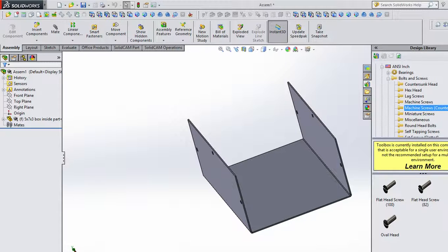Nominally means about. Whereas a socket head cap screw like that, the 1/2 inch refers to this dimension, just from the underside of the head to the end of the bolt. So be careful when you see 1/2 inch bolt. It means different things in different places. All right, questions there?